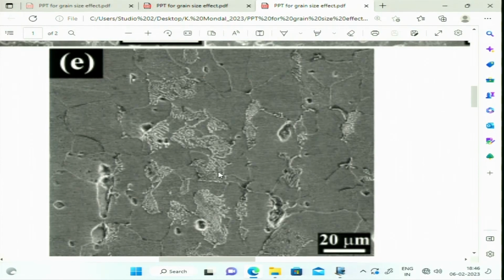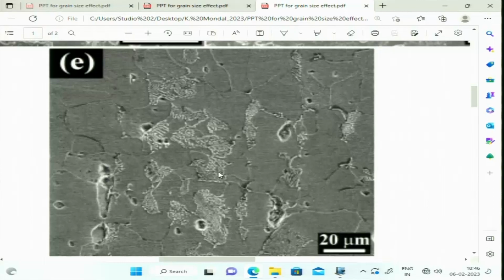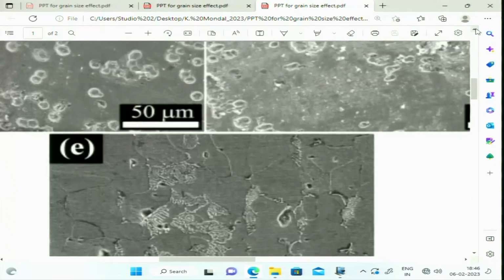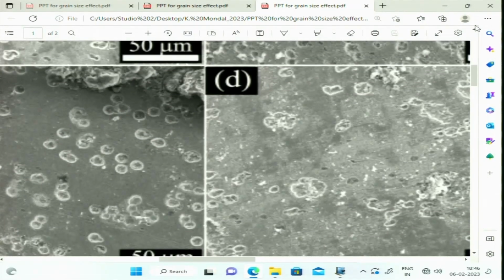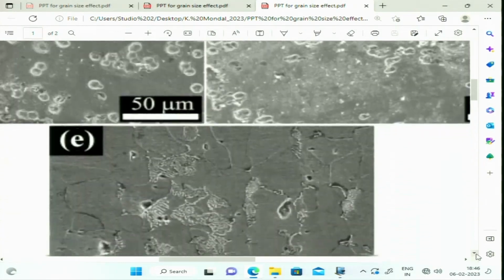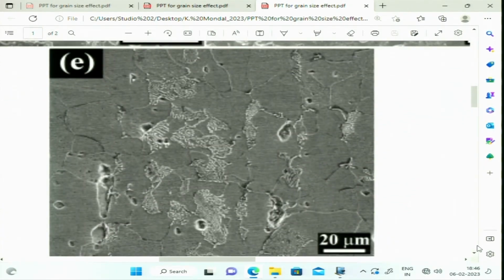and there, as per the phase diagram, the steel part of the iron carbon diagram, we can calculate what could be the amount of pearlite there. So, it will be a mixture of pearlite and ferrite grains, and we will also have an interface between pearlite colony and ferrite grain. Now, this material initially showed pits, but much fewer, and it did not show any signature of grain features, but here you could see that initially when we have taken it after doing polarization.